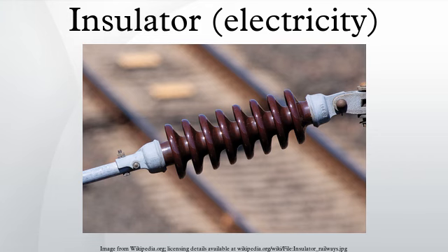Types of insulators. These are the common classes of insulator. Pin-type insulator. As the name suggests, the pin-type insulator is mounted on a pin on the cross-arm on the pole. There is a groove on the upper end of the insulator. The conductor passes through this groove and is tied to the insulator with an annealed wire of the same material as the conductor. Pin-type insulators are used for transmission and distribution of electric power at voltages up to 33 kV.